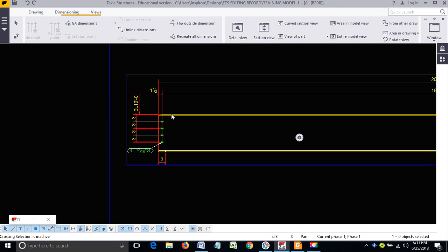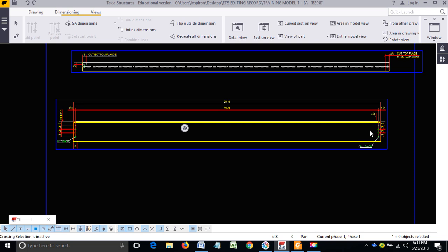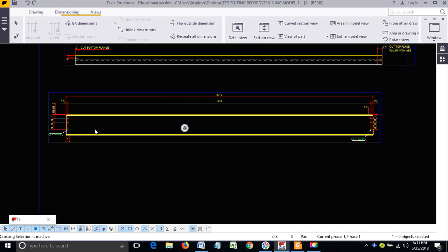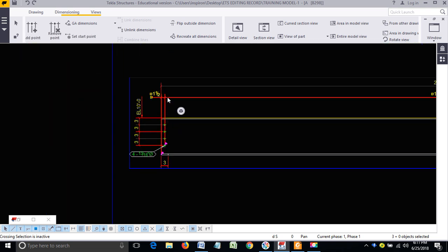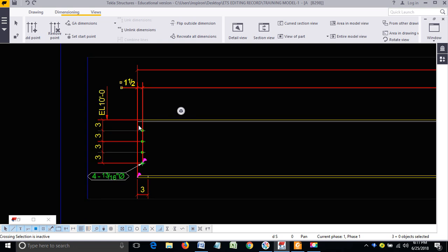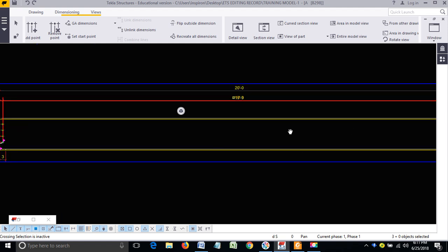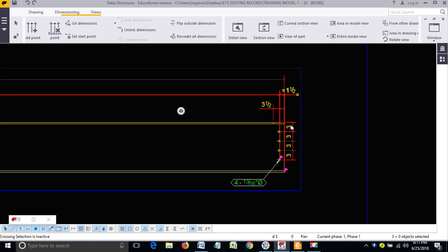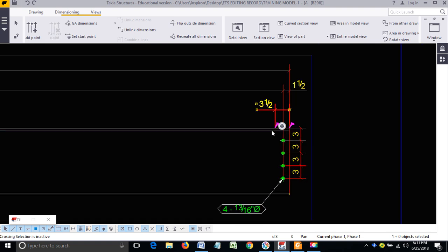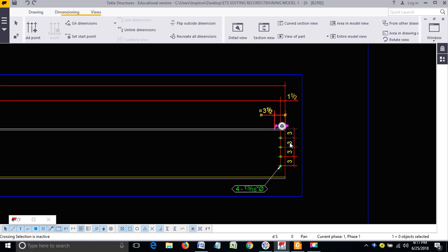The steel beam should always be clearly visible. Coming to the next point also, they are supposed to start at the top of the beam here, first point, and the second point should be here. They did the bottom of the beam, and it will be overlapping, and on the right side end also they picked the bottom of the beam. So this is what happened, and this dimension is extra, correct.